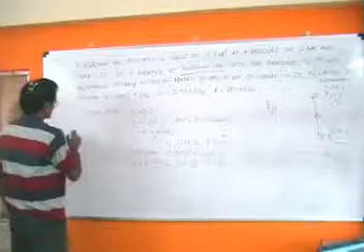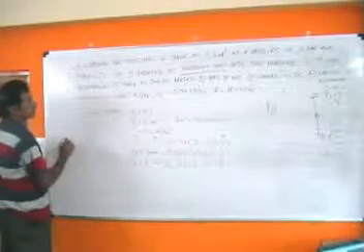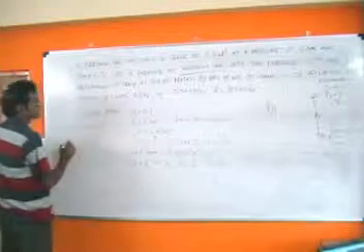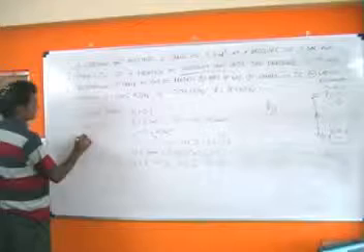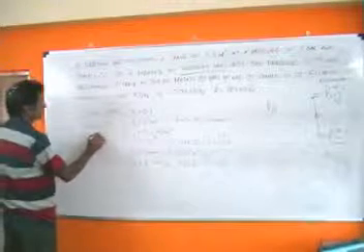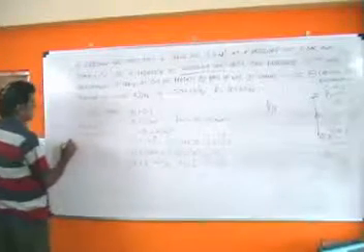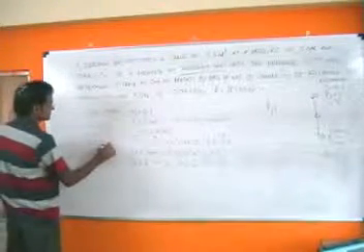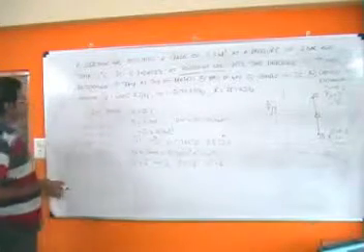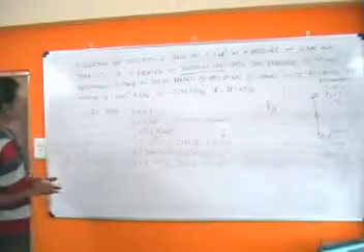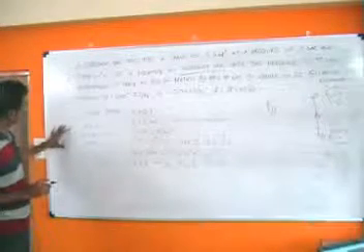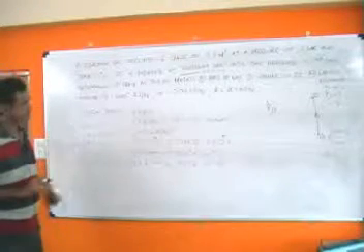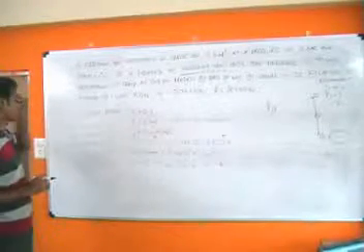And we have got the standard values given as R equals 287, Cv equals 0.712 kilojoules per kg, Cp equals 1.005 kilojoules per kg. You need to also observe the units of these constants. Sometimes the values of these constants are given in different units. So you need to convert them into the standard SI units before starting to do the problem. Now let us go one by one through the questions.